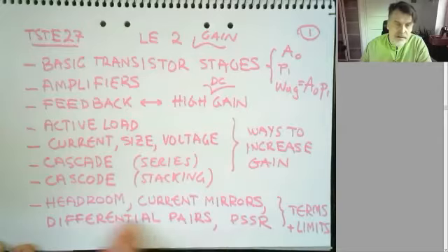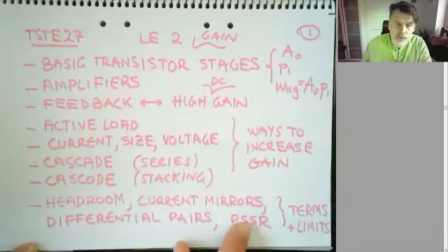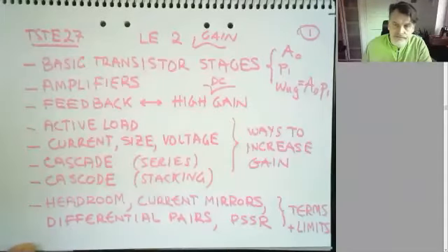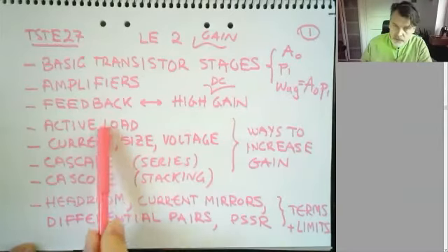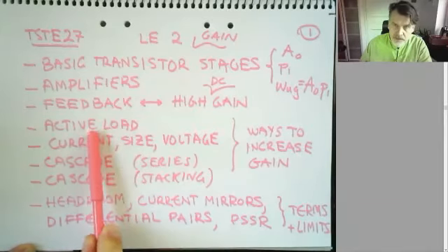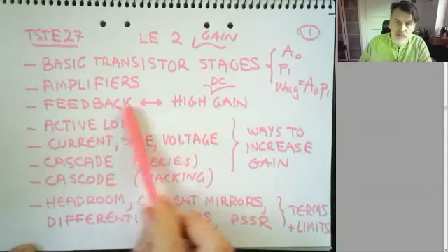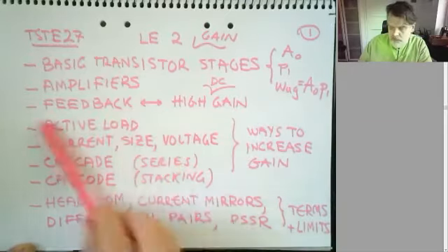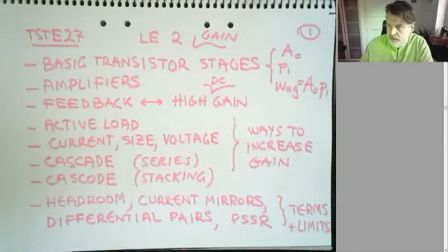And then we will add up with some more components like the differential pair, which you also recognize. We will do some extra calculations on that, which might be new for you, and then motivate why you want differential signals. And then with all that in place, we will have the differential pair, combine that with some sort of way here to increase the gain, to get a really high gain, and then we have operational amplifiers that we use in feedback loops. And then we're pretty set to use them in a switched capacitor circuit next lecture then.